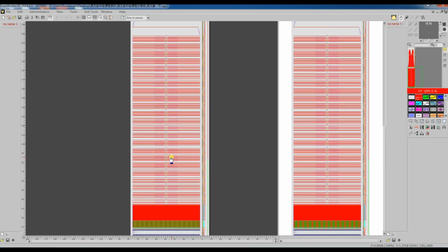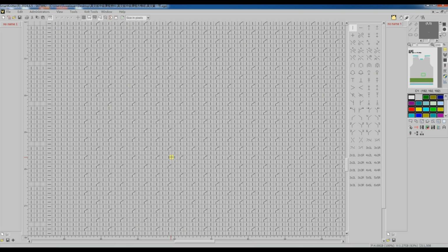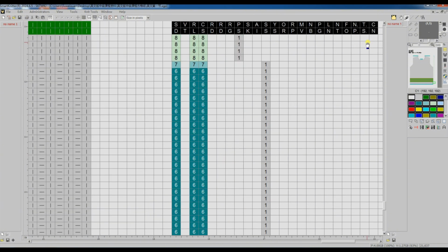If anything from the function lines are needed to amend, it is recommended to go back to SmartGraph before translation for editing. This is to make sure all the amendments are saved in the SmartGraph and would not be overwritten when retranslating the file into machine code. You can press F12 on the keyboard to quickly toggle between the SmartGraph module and machine code page.